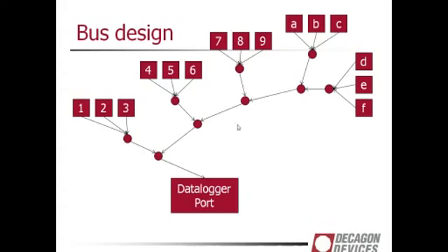You can start on either end or you can split things, but this is just one way to work on finding a problem sensor faster. Because you can imagine the more sensors you have on one data line, the harder it's going to be to find the one sensor that goes down. It could have gotten chewed halfway through by a rodent. It could have just had a problem.